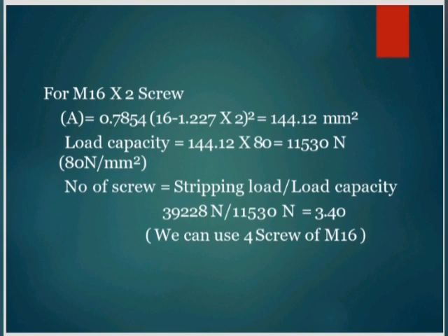So, number of screws is equal to stripping load divided by load capacity, which is 39228 Newton divided by 11530 Newton, equal to 3.14. So, we can use 4 screws of M16 size.